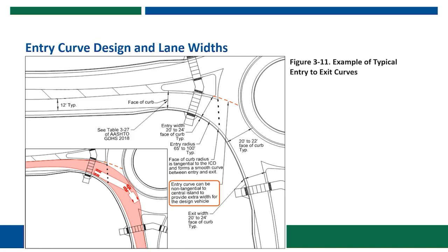The lane width may flare at the entry if necessary to accommodate large trucks, but we want to hold the right side curb line to maintain good speed control. We add lane width by reducing the width of the splitter island slightly. The figure does not provide a range for radii on the right side of the exit lane, but common practice is to use exit radii between 150 to 500 feet. Smaller radii may be appropriate where there is pedestrian traffic or constrained right-of-way, and larger radii may be appropriate at locations with significant truck traffic.